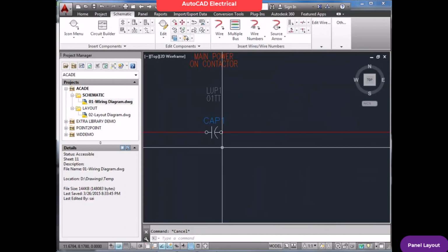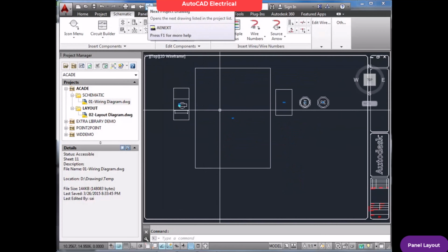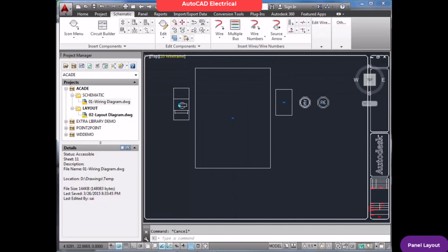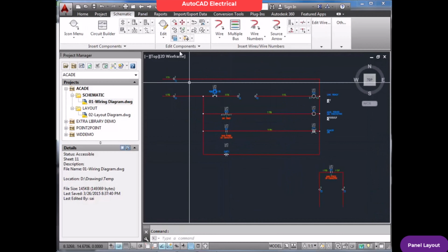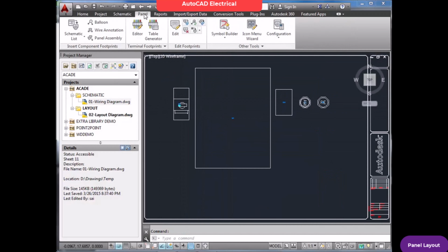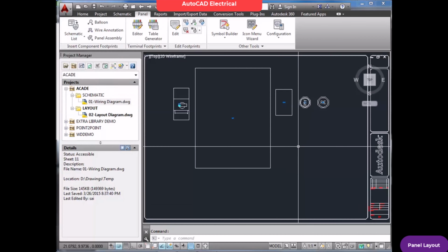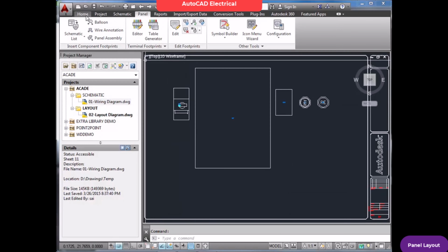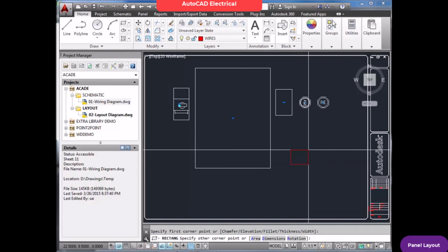Now I want to insert the footprint for the same, that is my capacitor, which is here in the schematic, this one, and I don't have the block for this. Then there is an option, that is manual, and assume that you know the size of that capacitor, you have the dimensions. What you can do is, as per your dimension, you have to make a diagram.